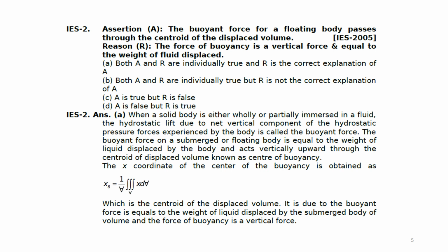Explanation. The assertion, the buoyancy force for a floating body passes through the centroid of the displaced volume, yes, this is absolutely true. And the reason, the force of buoyancy is a vertical force and equal to the weight of fluid displaced, is actually the definition of buoyancy itself. This reason is also the correct explanation of the assertion. So its answer is A.